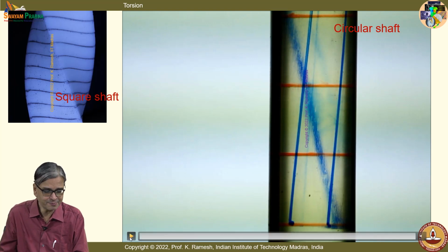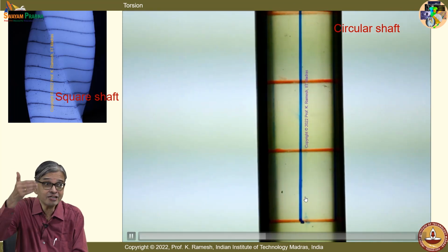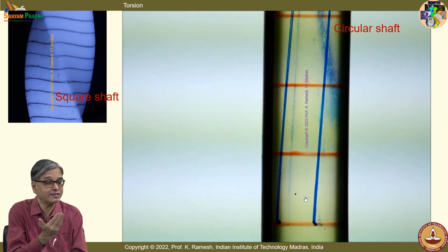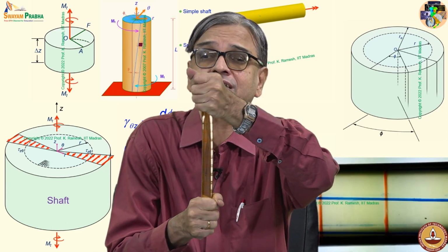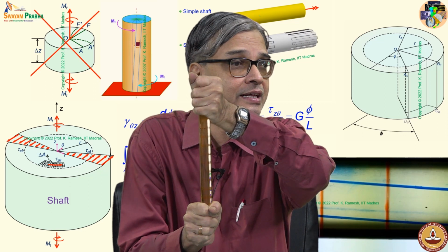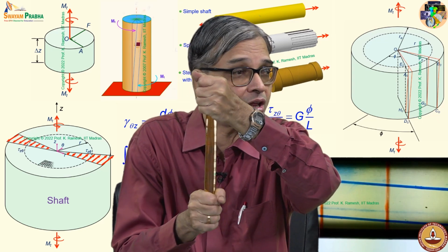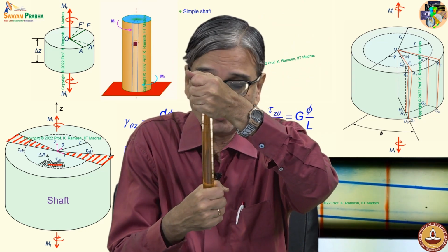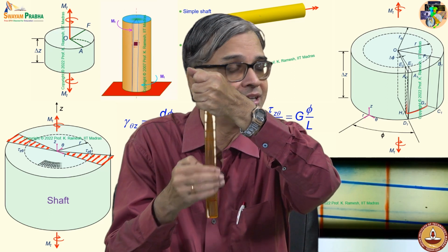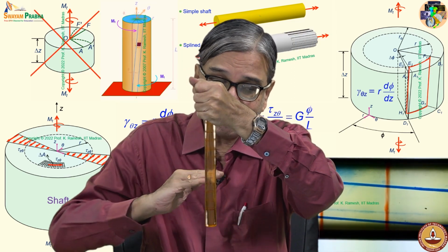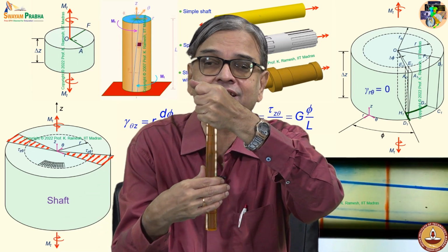Okay. And another aspect you have to look at is, we have also discussed free surface. The entire shaft is free on the outer boundary. See, how do I apply torsion? It depends on various aspects. When I want to do a demonstration, I have to hold it on either end and then apply it. And we are not applying whatever equations are developed in the zone where I apply torque. You all know Saint-Venant's principle. We move away from the load application points, we analyze what happens somewhere in the middle. And we have already seen when I apply a torque, every cross section here transmits the same torque. And you should recognize that this complete surface is free.